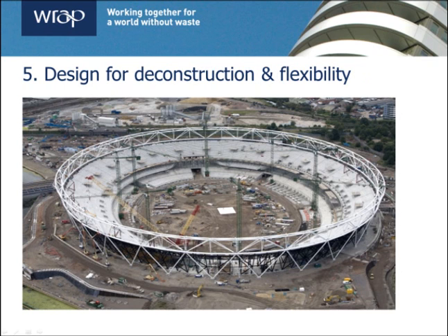The fifth and final designing out waste principle is designing for deconstruction and flexibility. While this may not produce immediate benefits for the designers and contractors at the time of building, this is best practice for the future and will ultimately reduce waste streams. Much of the waste generated by demolition occurs because buildings were not designed originally with demolition in mind, and a significant proportion could be avoided if materials can be separated out again effectively.